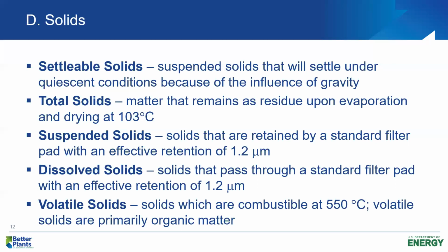So again, dissolved solids, we'll take a sample that we filtered. Well, usually what we'll do is we'll take a sample as is on the raw wastewater. We'll put it in a porcelain dish that's been pre-weighed to get the tare weight. We'll put it on a water bath, and we'll heat it for several hours and evaporate all the water in the sample. And there we'll leave all of the residual solids that were in the sample, and that's how we measure total solids. So dissolved solids then would be the total solids minus the suspended solids.